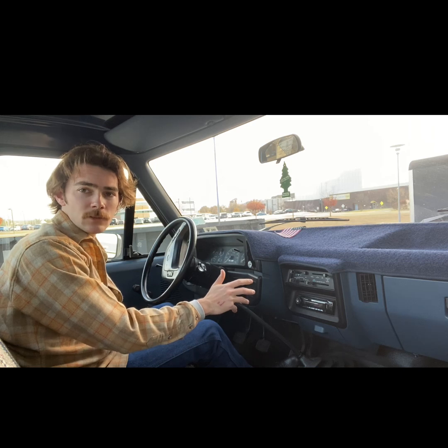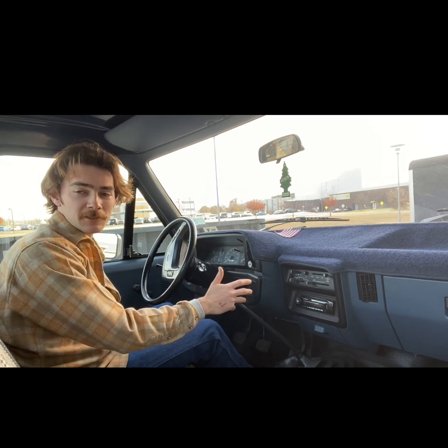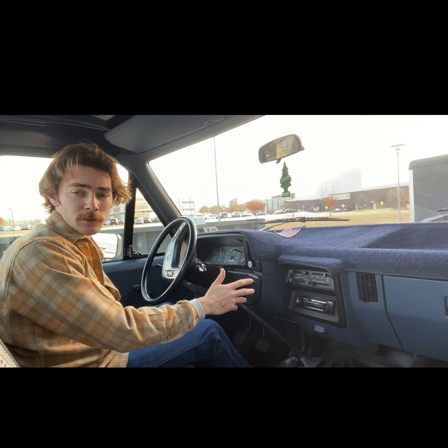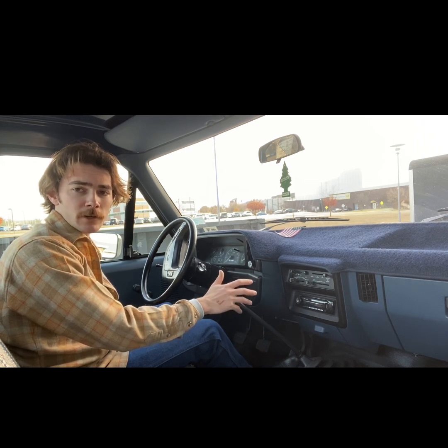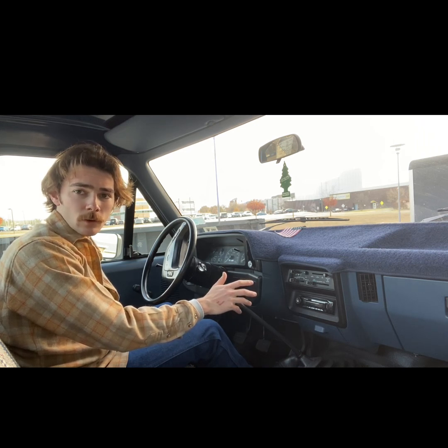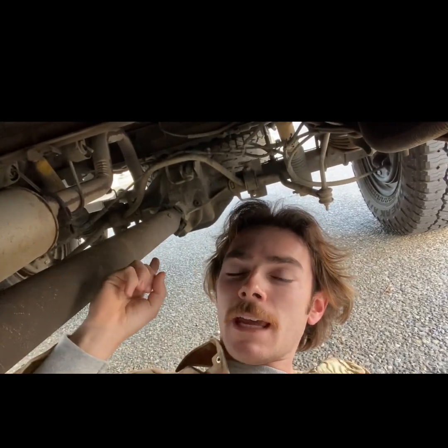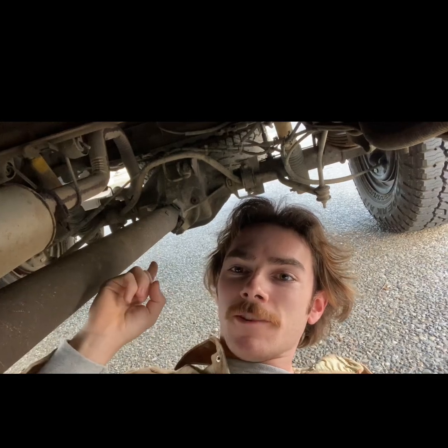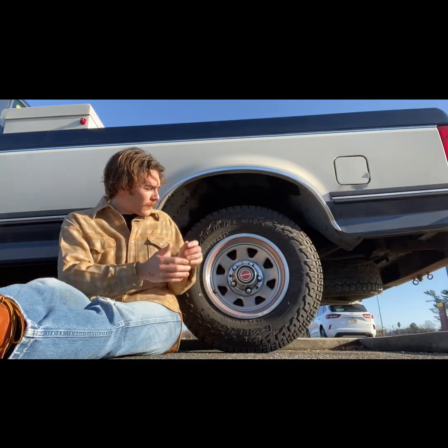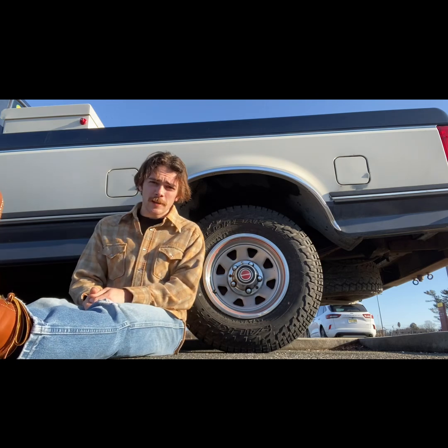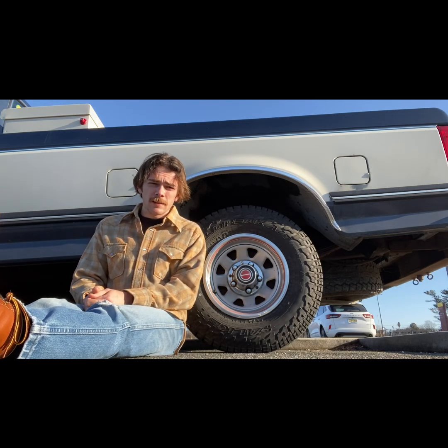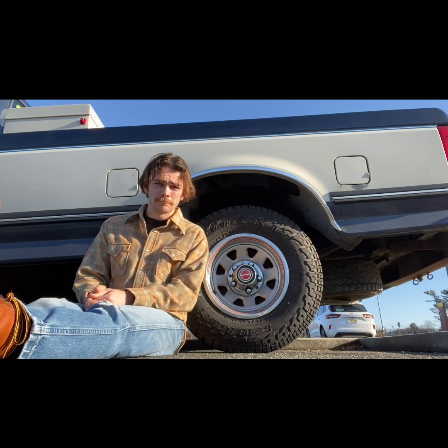It's a Tremec T170 FT RTS TOD, and it's a B-code transmission according to the door tag, which means that the gear ratios are a 3.25 first, a 1.92 second, a 1.13 third, and a .783 fourth gear or overdrive. The rear differential is a Ford 8.8-inch rear with 3.55 gears. This truck rolls on 30-inch Falcon all-terrain tires. It is rear-wheel drive, and in its single-cab, long-bed chassis configuration, it has a wheelbase of 133 inches.